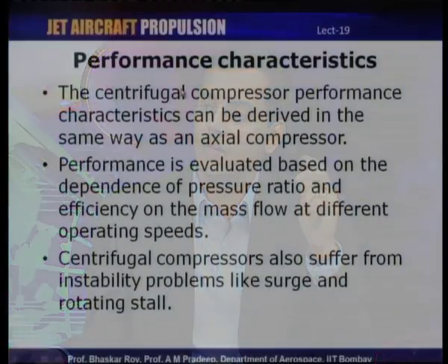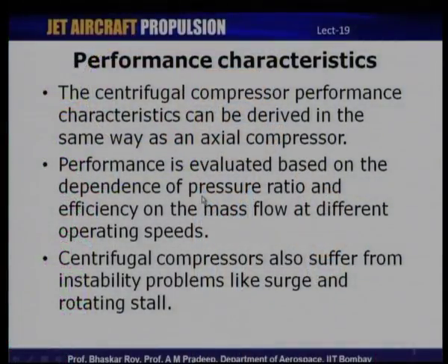The derivation of performance characteristics is exactly identical to what we had discussed for axial compressors, and we would be looking at the dependence of pressure ratio and efficiency on mass flow rates at different speeds. And what we will very soon realize is that centrifugal compressors also suffer from instability problems like surge and rotating stall. That we will also take up for discussion after we talk about the performance characteristics.